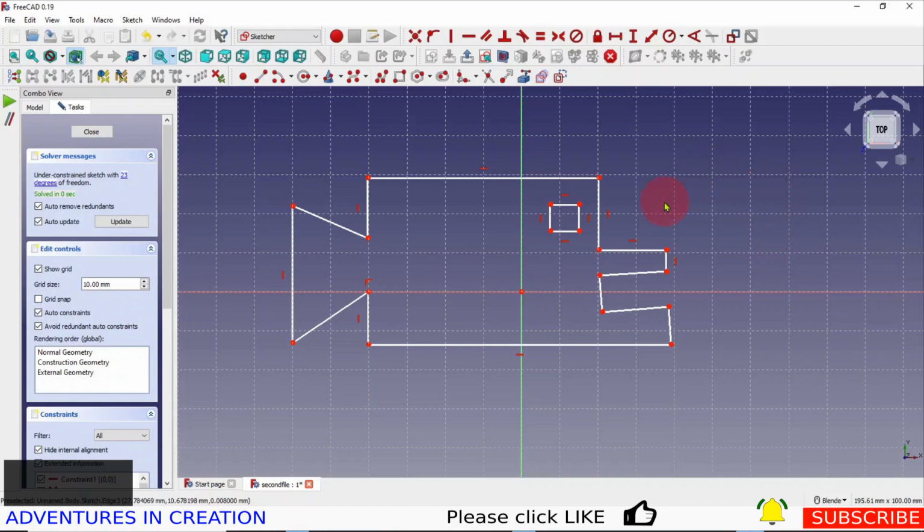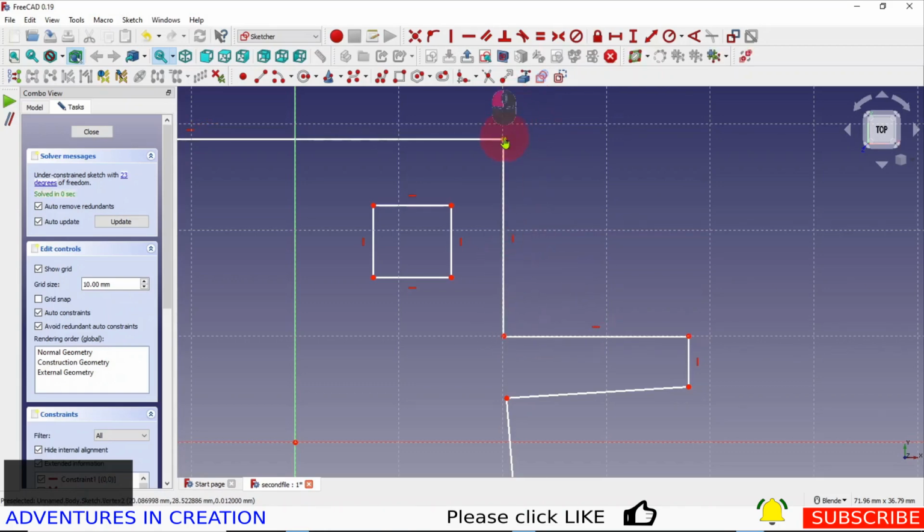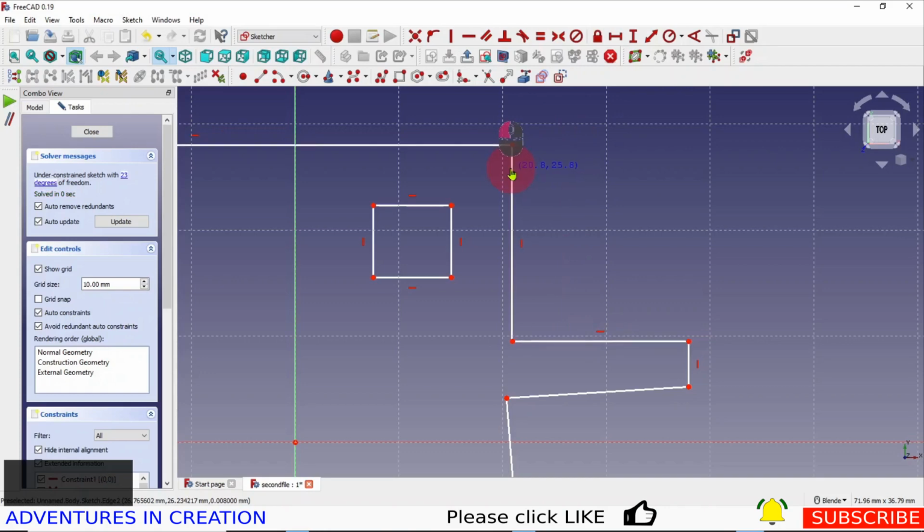Now, one thing I wanted to show you, if we zoom in here a little bit, you can see these constraints. This constraint is saying this line has to be vertical. So if I try to move it, you see the line moves vertically. It won't allow me to shift those points in different places. They're vertical, so they have to remain vertical. Whereas this line here, you can see it didn't get a constraint for horizontal. So this line got a constraint for horizontal. So if I move that line, it's going to move the whole line. If I move this one, I can shift the points around because it's not horizontal.